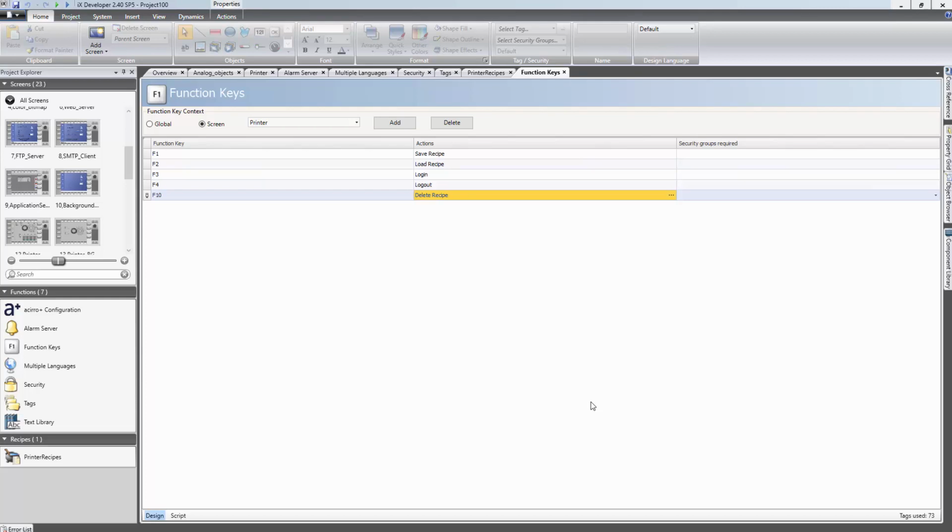After completing the conversion, all functionality must be fully tested in the target, in the same way as when developing an application from scratch. This means reviewing and testing all screens, buttons, I/O, etc., to make sure that the conversion has not changed the behavior of the application and that it fulfills all requirements. You might need further editing and refinement of the application before it fully matches your requirements.